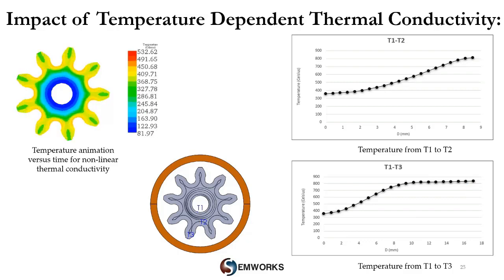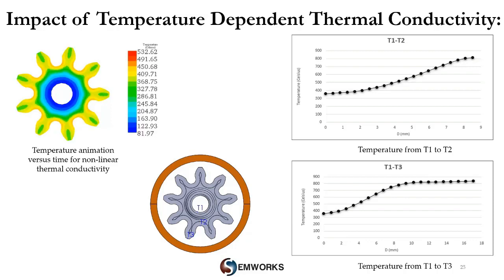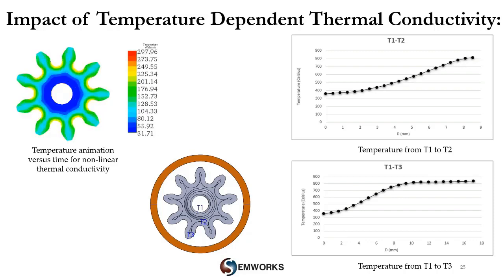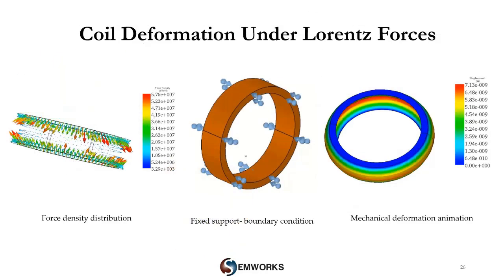Now what about the generated electromagnetic and thermal stresses? High current may result in higher thermal stresses and Lorentz forces in both gear and inductor parts, which lead to structural deformation. EMS can be used to analyze this behavior. In addition to temperature, EMS computes Lorentz force in conductors with currents, and both of them, the thermal response and the electromagnetic, including the Lorentz and magnetic forces.